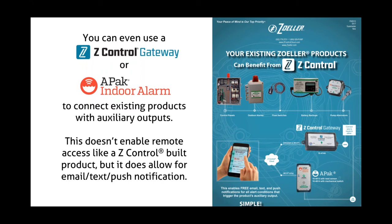Many of those have dry contacts. Our previous generation of charger has dry contacts on the bottom of it. So does our smart pack. A switch, a mechanical float switch, is in essence a dry contact. So any of those things can be monitored by the gateway and the APAC, even if they weren't designed to work with Z-Control. So how do you do that? You just take a 2-conductor wire, connect it to the dry contacts or auxiliary output on the device.